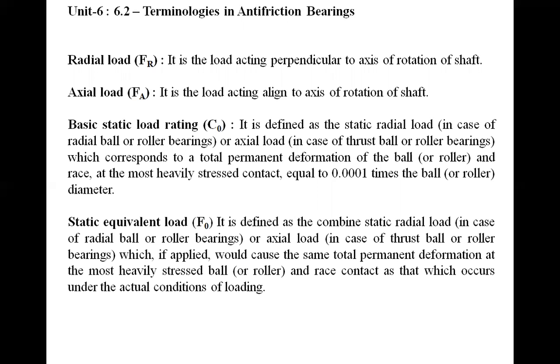If the compression is within the limit, that is 0.0001 times the ball diameter, then that loading is the basic static load rating.